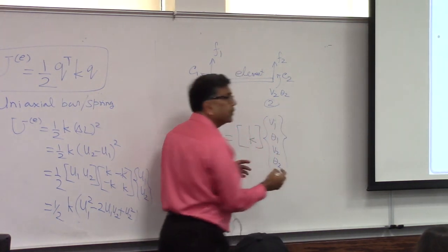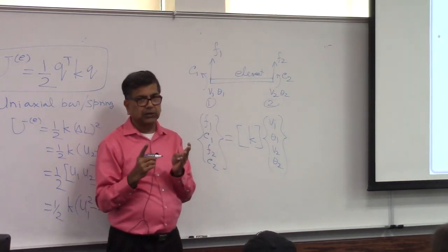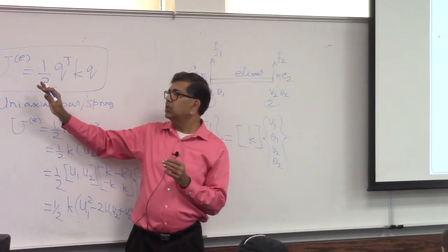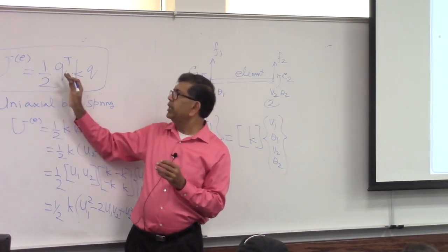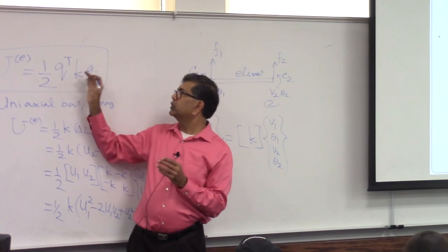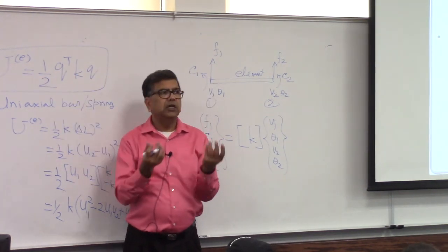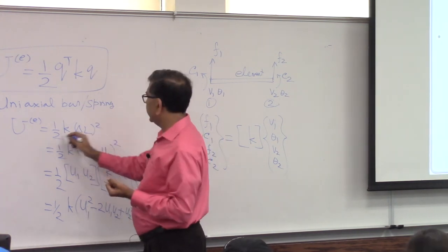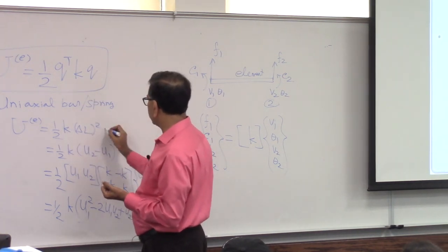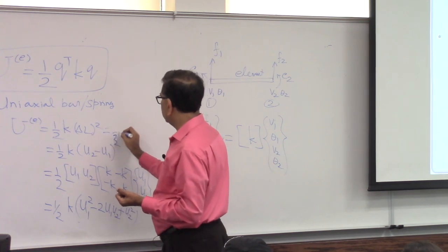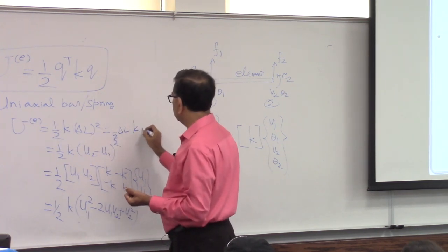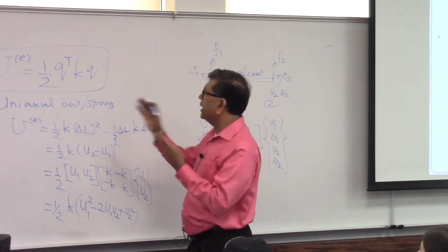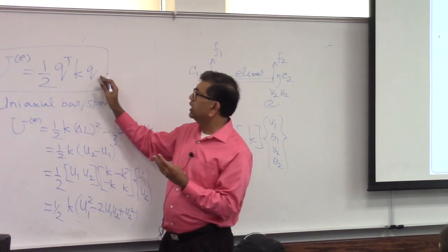So there are 2 interpretations for the element stiffness matrix. One is this interpretation. Energy method claims the stiffness matrix meaning is that 1/2 Q transpose KQ is the energy. What is the energy in the spring? 1/2 K X square, that is 1/2 K delta L square. In the same form, you can write this as 1/2 delta L K delta L. Same idea, 1/2 Q transpose KQ.